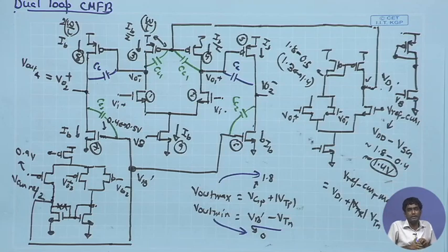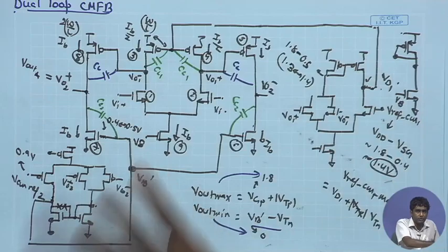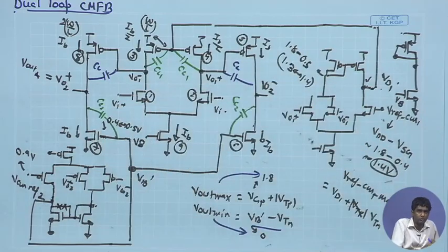So, in this case, you have to just keep track of the discussion that we had in the last day, where we talked about opening the loop in simulations and how to do the bias while keeping the DC points intact at different points. So, for the dual common mode feedback loop also, you have to make sure that while you are opening the loop for the DC or the stability analysis for these individual loops, and then for the differential loop, the DC